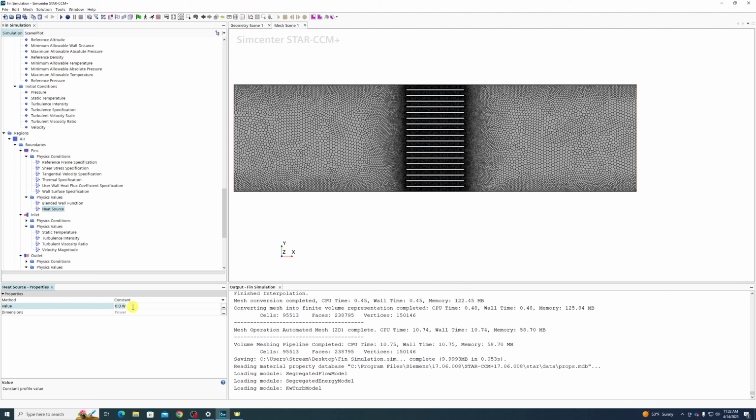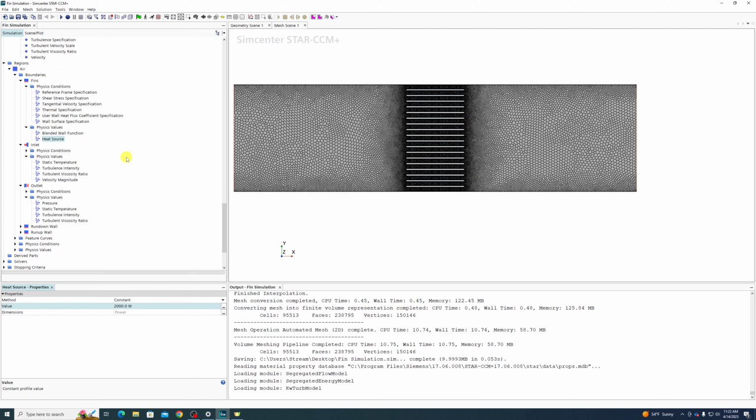Let's do, and this is about as big as a CPU heat exchanger, except it thinks it's 1 meter deep, which it's not in reality. So it's probably about a tenth of that. So we're actually going to kick up our total heat source to 2,000 watts. About 10 times computer processor size, because this is about 10 times the area of a typical computer heatsink. Order of magnitude. And see what happens.